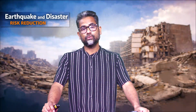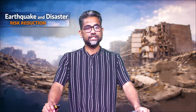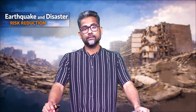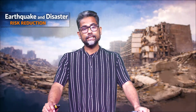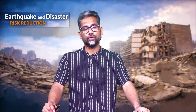Building codes and seismic design standards. The Bureau of Indian Standards mandates earthquake resistant design through key codes. IS 1893, that is criteria for earthquake resistant design of structures. IS 4326, that is earthquake resistant design and construction of buildings, and IS 13920, that is ductile detailing of reinforced concrete structures.